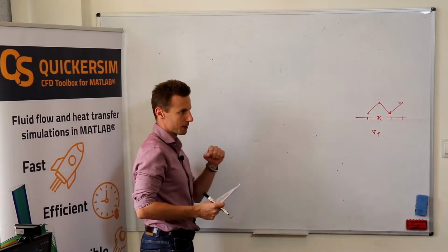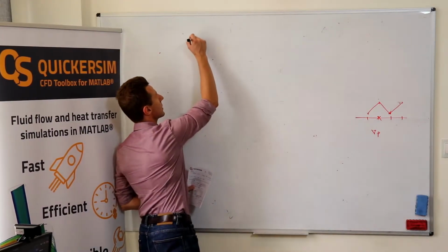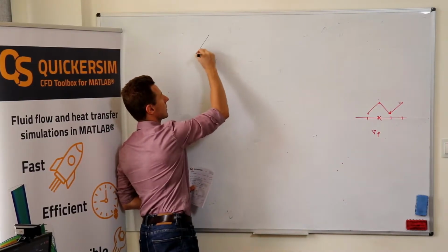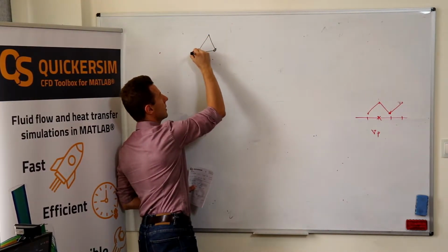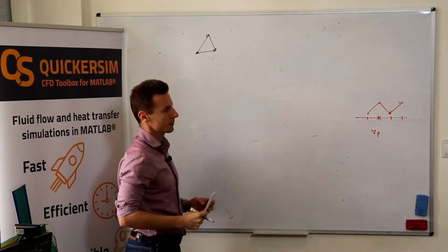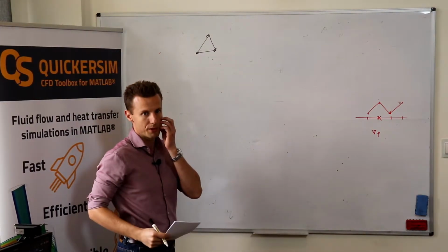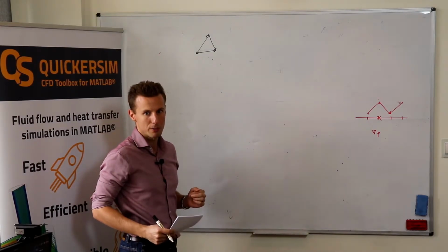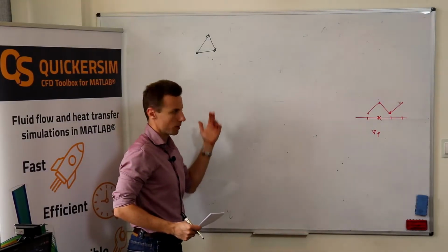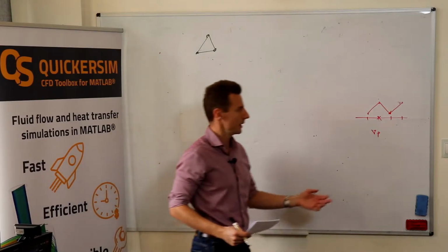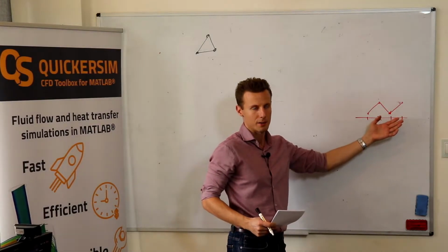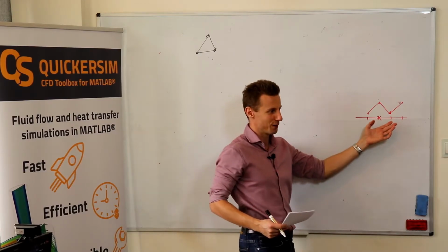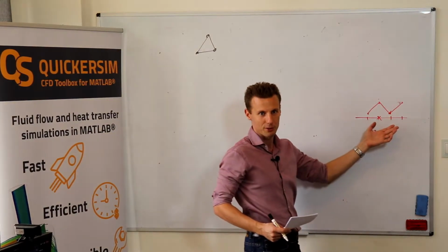You simply can't, because this will always be unstable. If you select such triangular elements to discretize the velocity space and the pressure space, it will be wrong. It will be unstable. The proof why it's unstable is for a longer lecture, not for now.